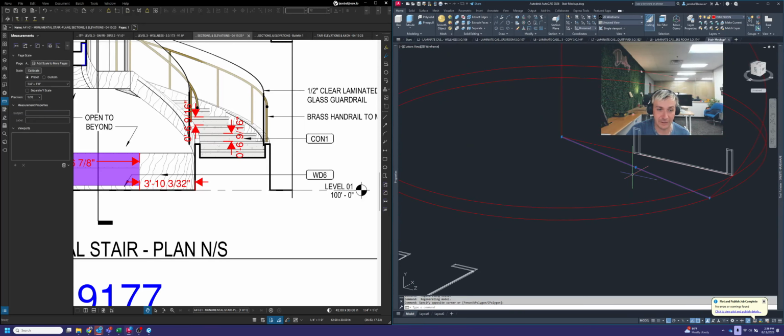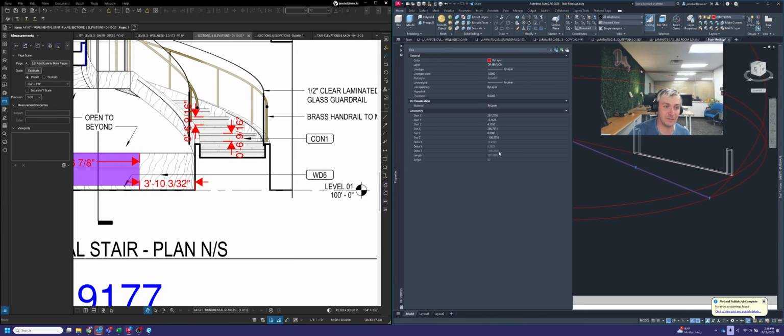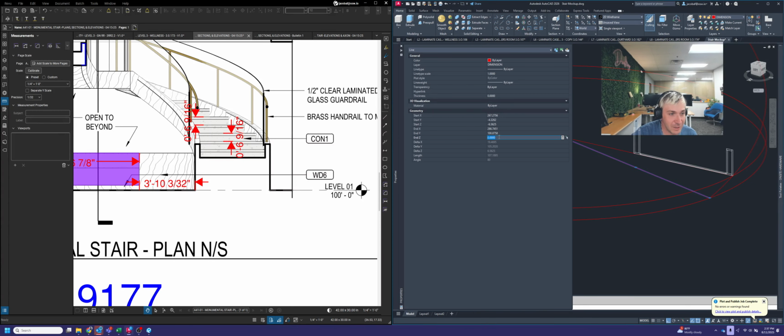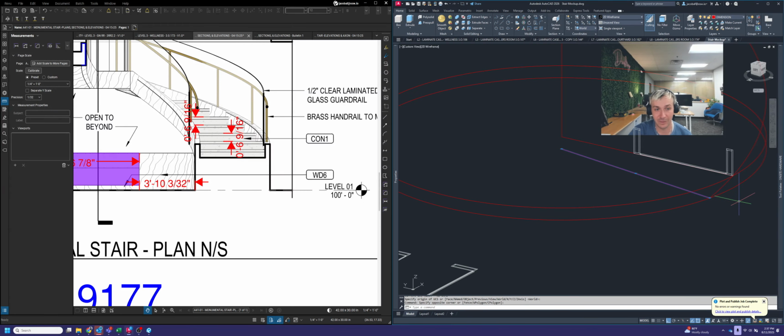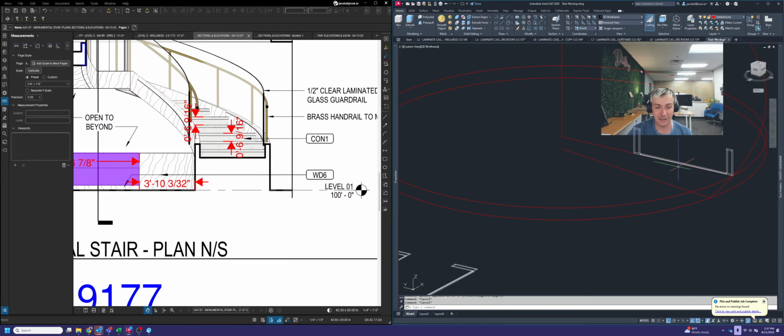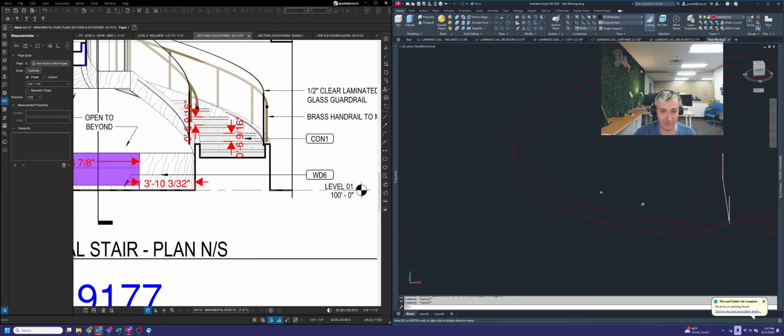So what I need to do is highlight that line. A lot of times with these helixes, you can go into properties. I think Cody showed me this a long time ago, but you can change your end and start points for each point. First I have to make sure I set this back to WCS. My end Z is at 0 right now, and my start Z is at negative 6.5625, which is where I want that to go. So I can change it in properties and it'll change one side but not the other. That's kind of neat. If you haven't messed with that yet, it's a nifty way to cheat the system a little bit.